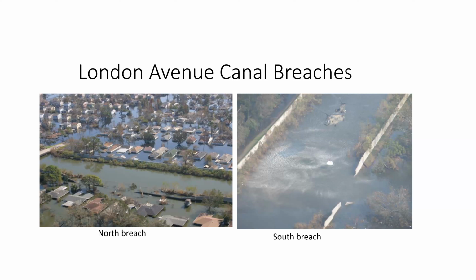So why only this location? Why not other locations? Other locations also have the seepage and water. So why didn't they create the uplift? Why this location? Due to the geologic condition, the soil condition in this particular place. It has sand. Other locations don't have sand. No, some locations have sand. There's an issue with the joint. Well, it depends on the clay layer on top of the sand, the clay blanket. Related to hydraulic head.